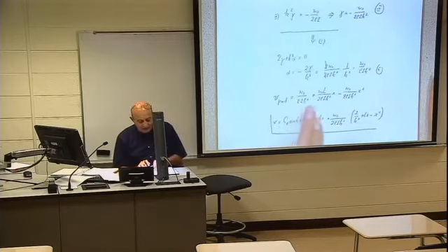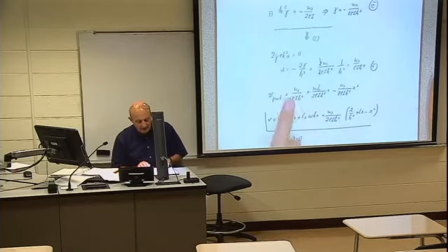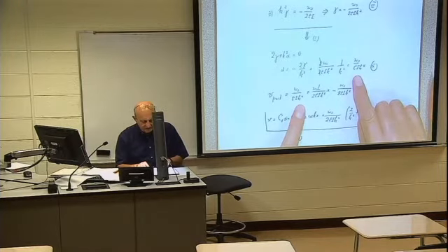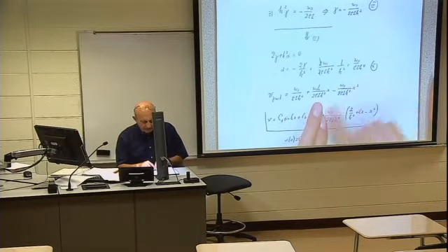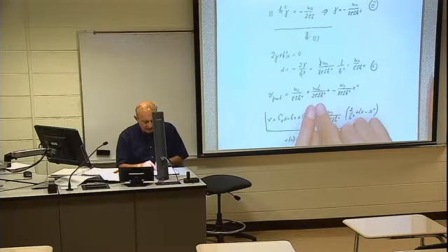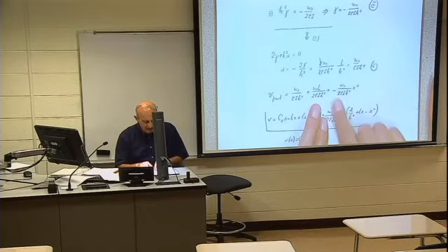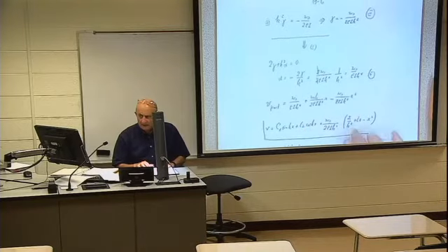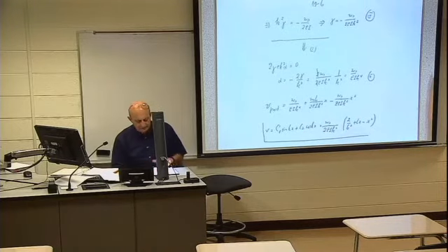So that is an equation then, V particular. W0 over EI k to the fourth power, that is this term alpha, plus beta, W0L over 2EI k squared, that is beta times x. And then gamma, minus W0 over 2EI k squared, x squared. I will wait so that you could write down.